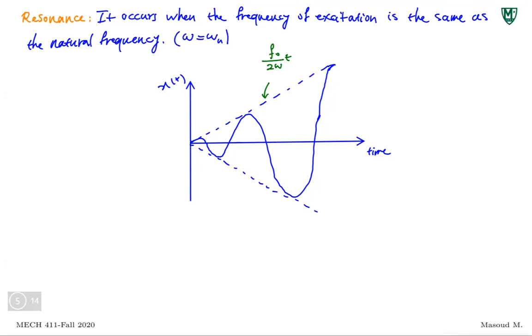Then it's a problem. So you need to know the natural frequency of whatever part you're making in a mechanical system, and you need to also be aware of possible forces that are going to apply to your part, your structure, or your machine during its operation, and make sure that they don't get close. Specifically, they don't become the same.